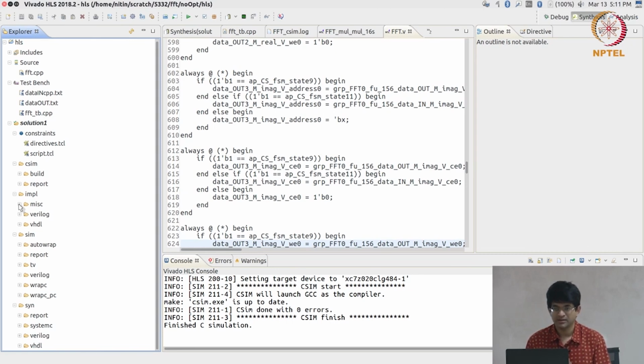And think about it, it is not at all obvious that that is actually happening, because what you had originally was a C code, and now what you have is a Verilog code. What proof do you have that they are both doing the same thing, except for the fact that Xilinx basically gave you some assurance that their compiler works? The unfortunate part is there can be situations where the compiler has bugs in it and actually generates Verilog code that does not work the way that you expect.